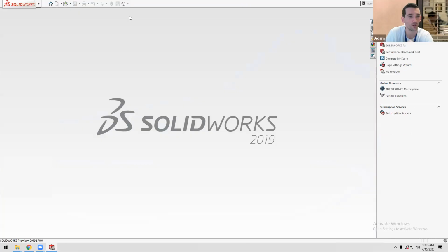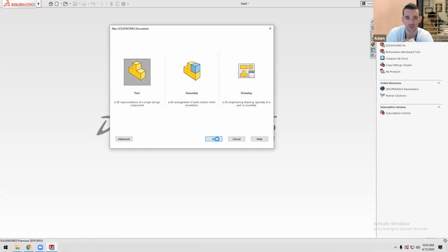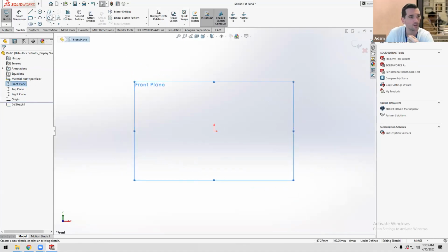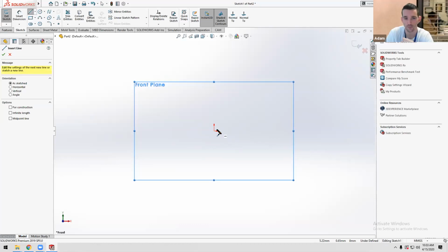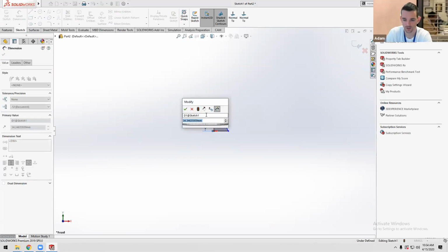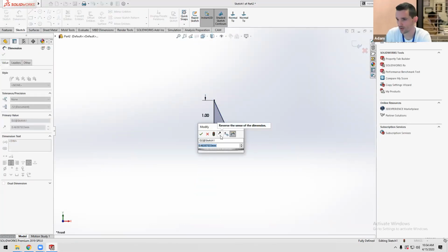Let's do one more part with Revolve. If I have rotational symmetry in a part, I may want to revolve something. So in this case, I'll do a quick microneedle. Let's do a microneedle patch. So I'm going to make a cross section of a single microneedle. It's 1 millimeter tall, and it's 300 micron diameter, which would be 0.3 divided by 2, sorry, for a half here.